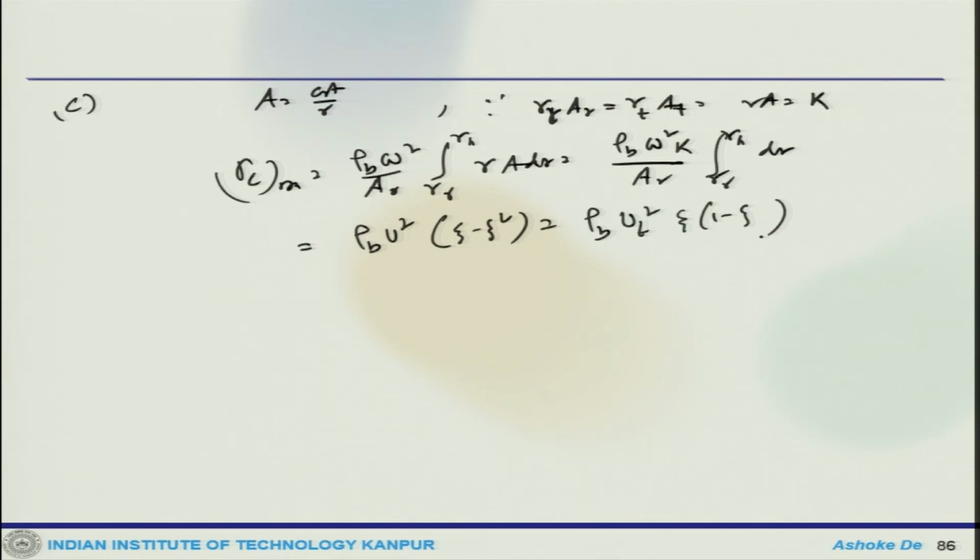So, the same equation can be applied for both fan and compressor. For a fan, the blade height is long, which develops a large tip rotational speed, and the hub to tip ratio is small, thus the tensile stresses are expected at the blade root. So, the same thing one can apply to both compressor and fan.